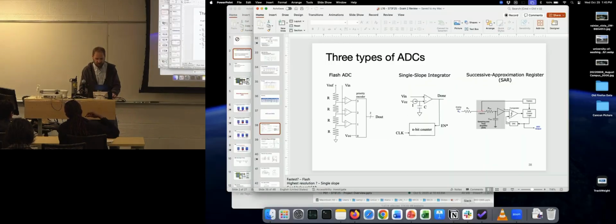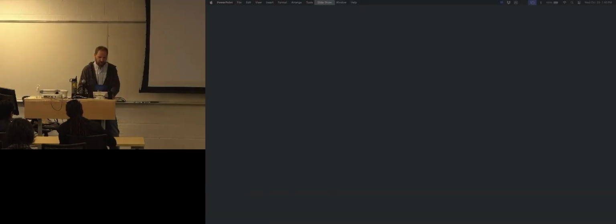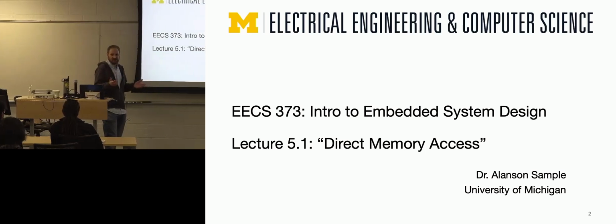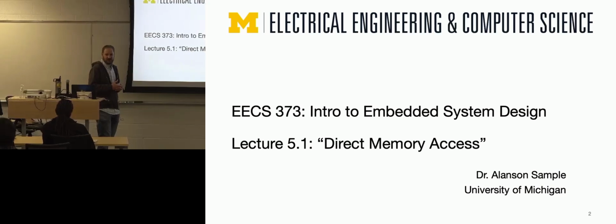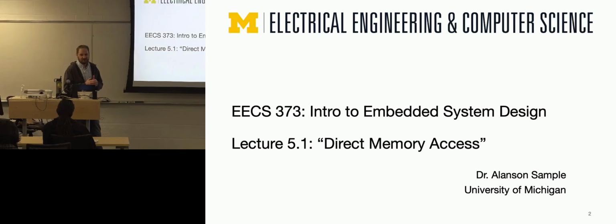Sampling rate, that typically is using the oscilloscope sample rate rule where you just do 5 times. I would say the most robust way is to use Shannon's limit or Shannon's theorem for sampling. This is how fast you have to go. An oscilloscope is for you to look at things, to be able to look at a signal and understand it without using math to interpret it. So if you're going to sample something in the real world, you should probably go 5 times faster. It's just my rule of thumb for all of you. The question is use Shannon's.